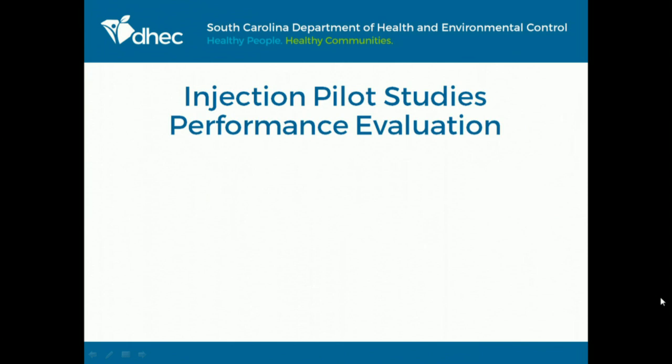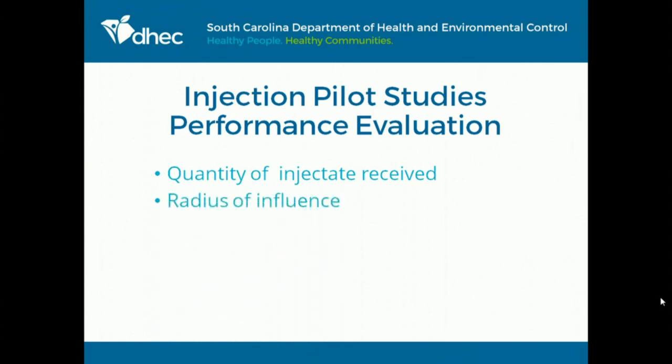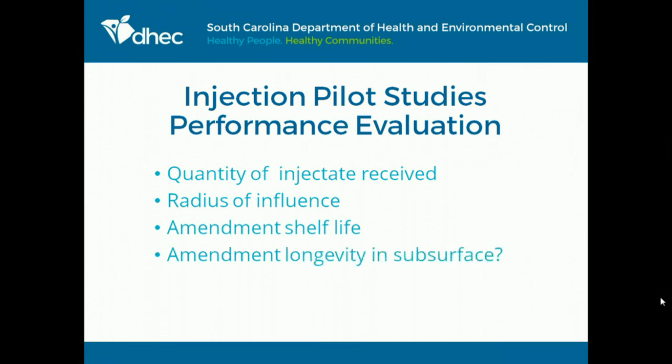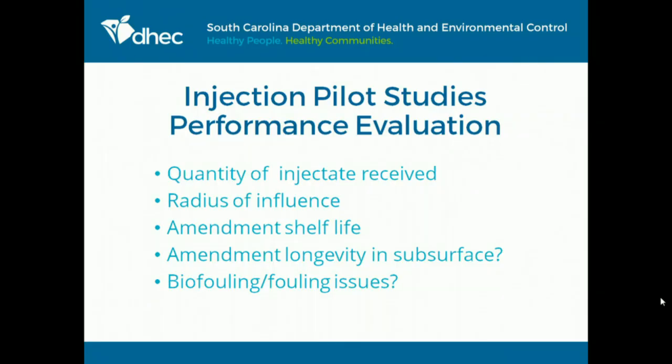So here are some performance evaluation questions. How much injectate is the ground able to receive? What's the radius of influence? How long is the amendment actually going to last on the shelf? How long is the amendment going to last in the subsurface? The companies that implement these technologies all the time have some idea of this, but subsurface conditions vary from site to site. The pilot study is going to help you with that.